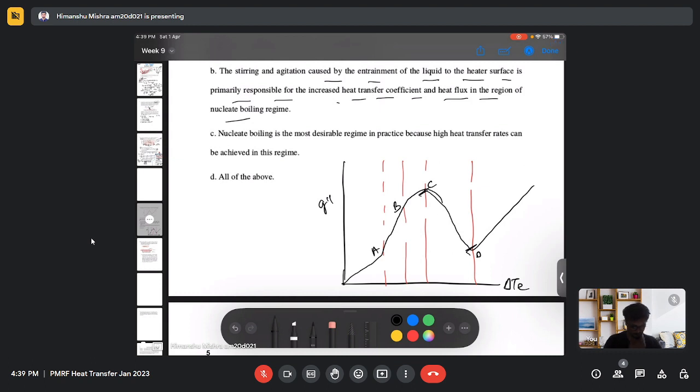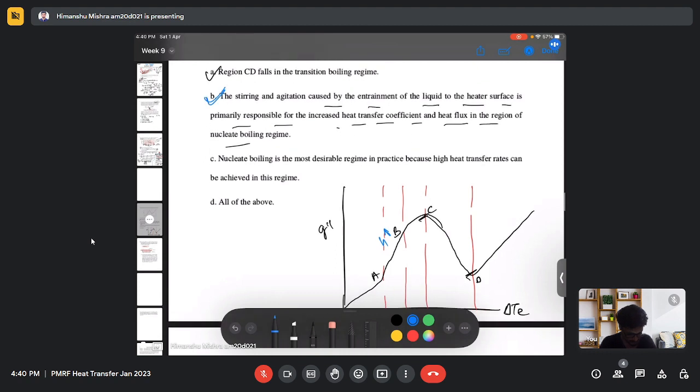That is true. Basically there will be an increment in the heat transfer coefficient due to the mixing of different kinds of bubbles and the fluid, and these bubbles try to combine and form a slab, and during this process there will be an increment in the heat transfer due to this highly turbulent nature, as I explained at the beginning of this class. So this is also true.